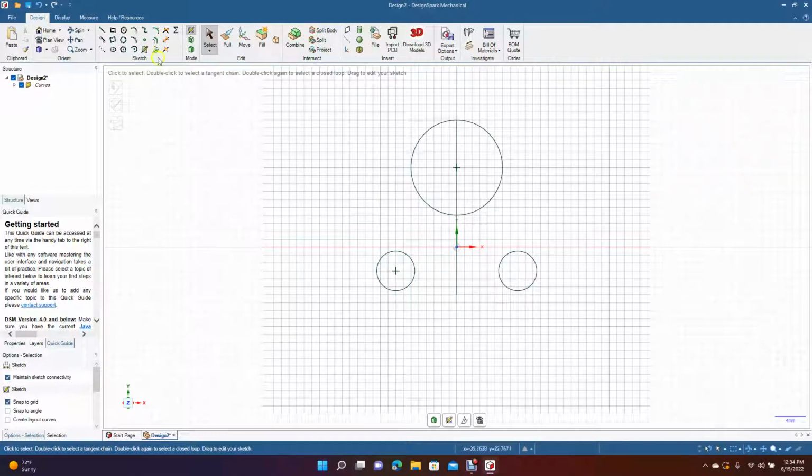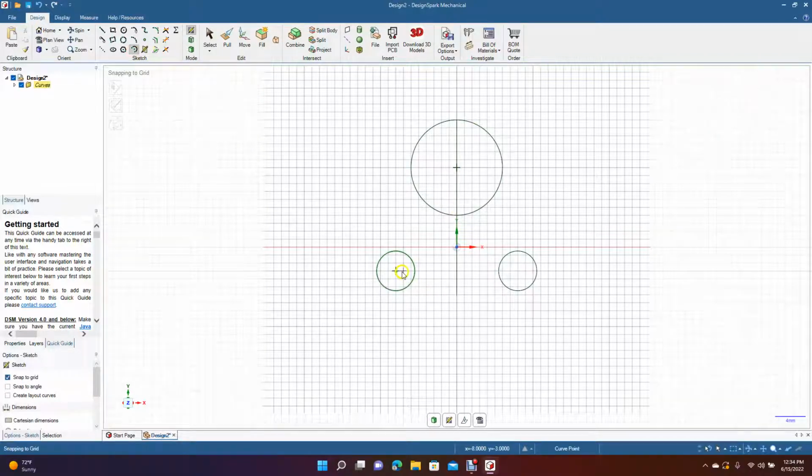Now we're going to go ahead and get this sweeping arc. And we're going to go from here, just follow this midpoint over, center point to there. We're going to click. We're going to drag out to here. Click another time, and then we're going to round this.